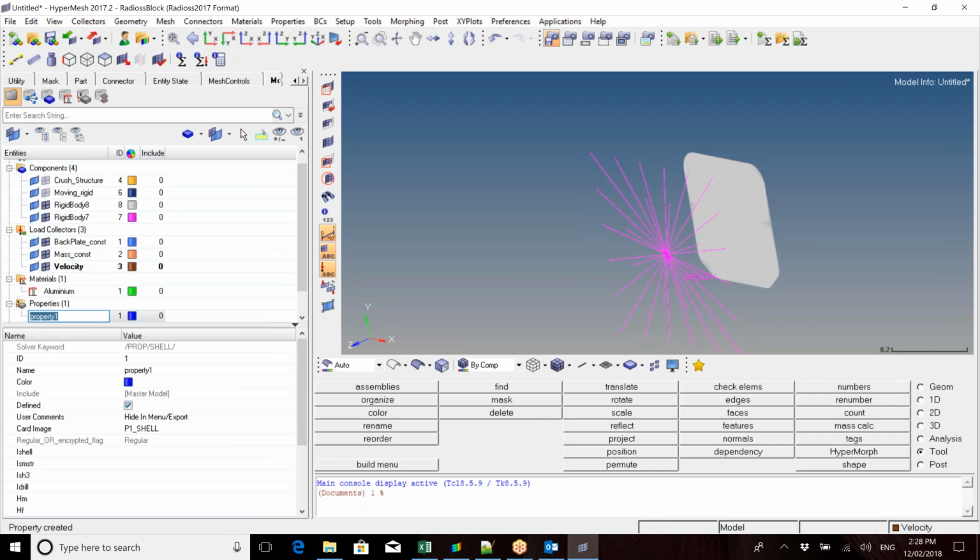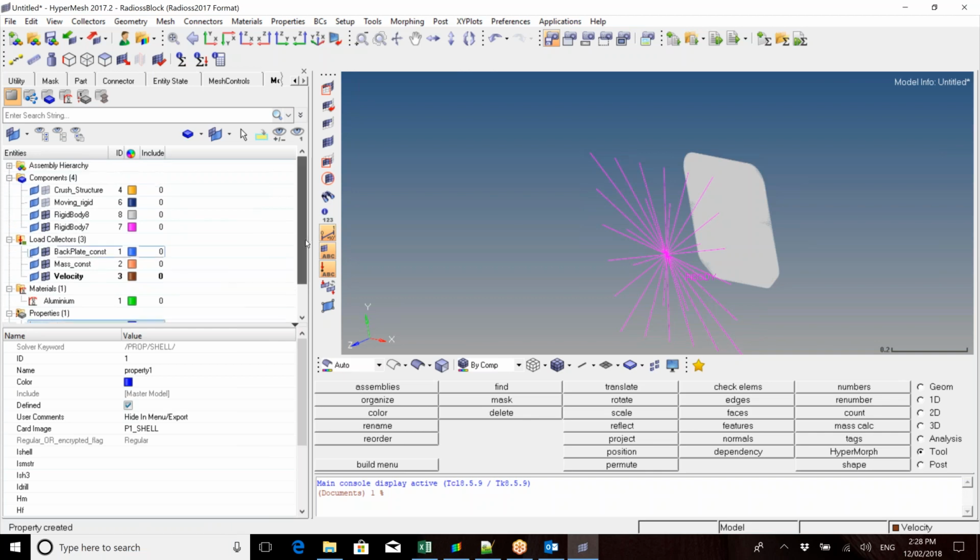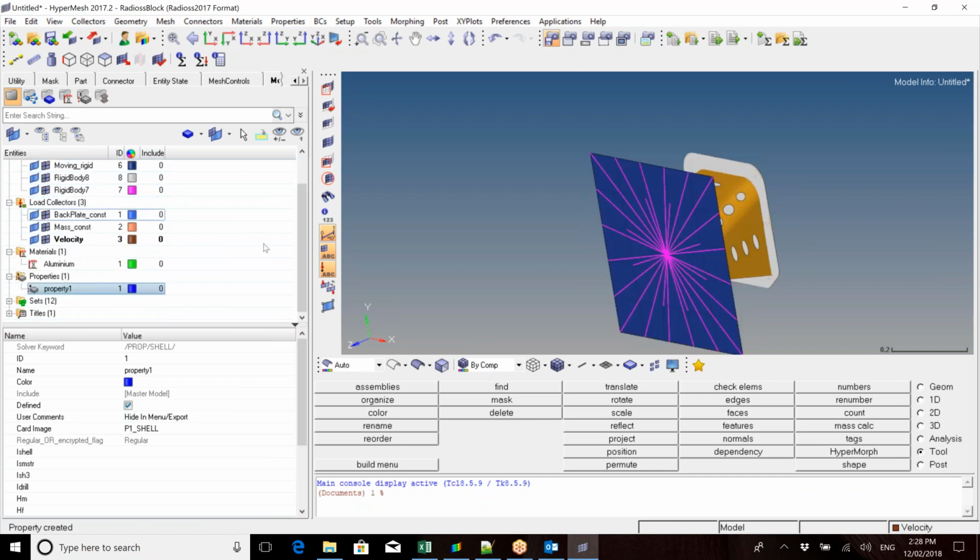Okay, so for this, there are a few different properties that you would be looking at depending on the type of elements that you're using. The main elements that everyone here would be using are your basic tetra and shell elements. They're probably the most recommended for any general shell structure mesh anyway. They're also a very good default as to both analysis usage and computational taxing, so computational time to the closeness of results. So I really recommend trying to stick with the shell elements.